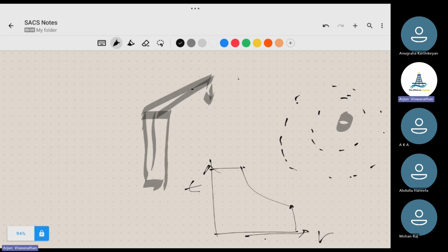Now we have certain limitation regarding the height of the hook. So we need to make sure enough hook height will be there. We cannot just increase it like that. So people used to say, okay, minimum is 60. Can I keep on increasing? No. We need to check with the installation team if there is any constraint regarding the hook height, what is the minimum hook height I can use.